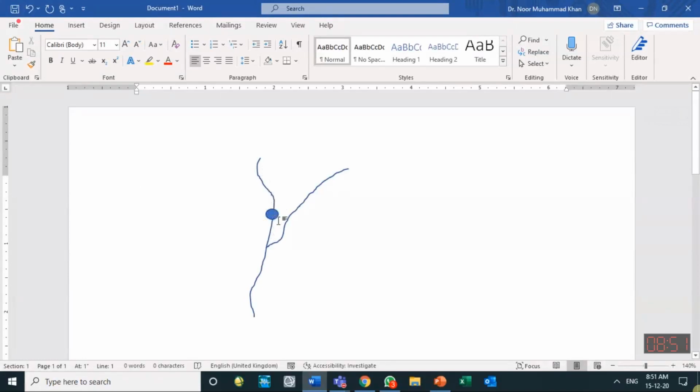So if there is a tributary coming over here on the downstream side of this stream gauge, and this tributary size is quite high, when it joins water to this place over here, there is possibility that this water goes up also, in addition to going downstream. So depending upon the channel slope, some effect of this tributary can proceed on the upstream side also.